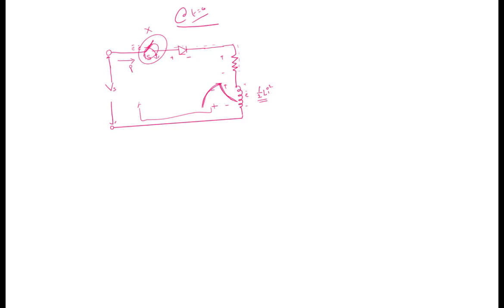For this reason, to recover this trapped energy, we should use a diode called a freewheeling diode. It should have less recovery time and fast operation. So what actually happens is, whenever this energy is trying to discharge, instead of wasting the energy and blocking the switch, you can freewheel the diode here itself. This type of operation is called freewheeling diode.